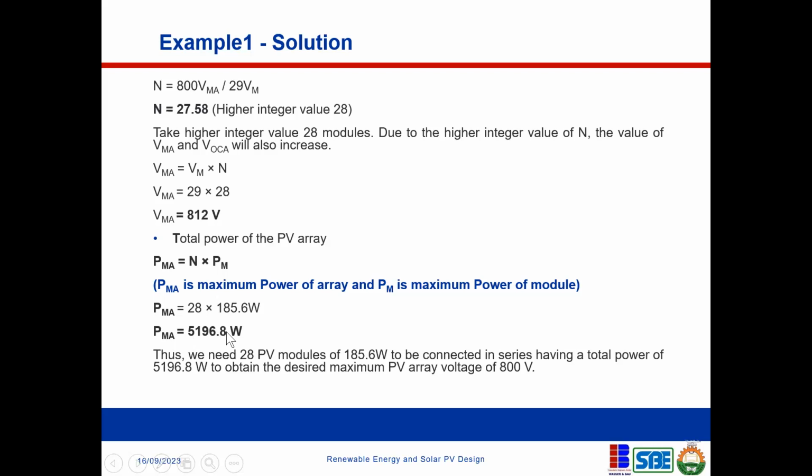Now, you can see that this output is not even up to 1 megawatt. What this means is that there has to be another series connection, which you then have to connect in parallel to get the kind of output you want. If you want a 2 megawatt output from that inverter, you need to increase your PV modules. But this is just for an example.